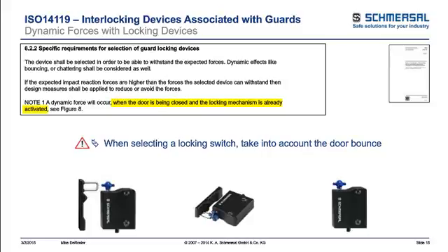So when you're looking at your guarding design, look at not only the fact that you have to have it closed and locked, but look at the foreseeable use on it, and is there bouncing, and how do you minimize that bouncing impact on the switch, whether it's built into the switch to handle it or external on the door frame and the door to soften those bounce backs so you don't get those mechanical forces hitting that switch that can cause that switch to become defective for you.